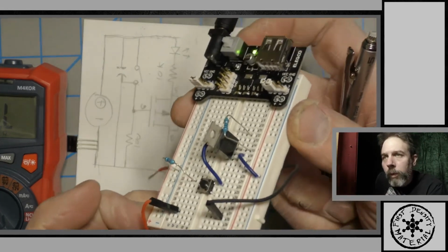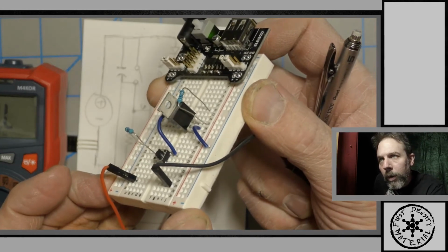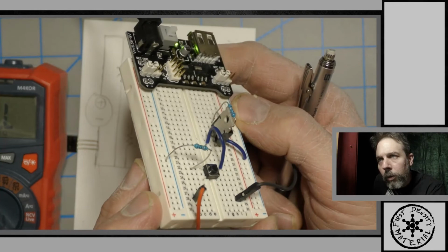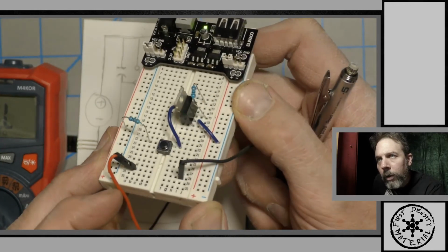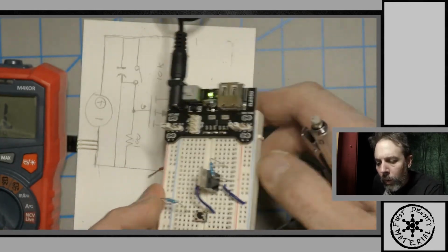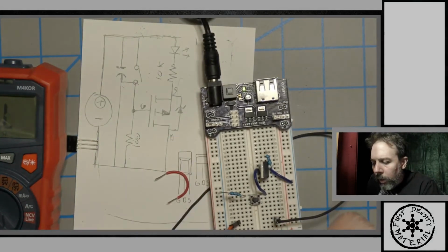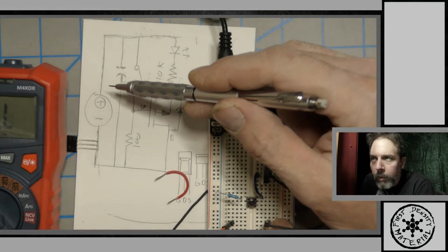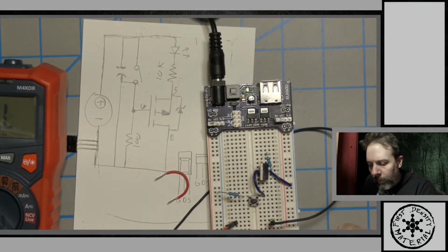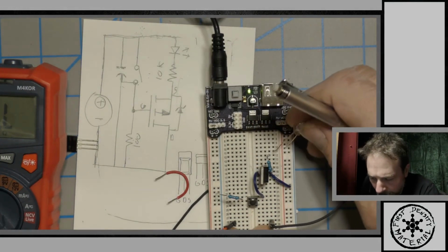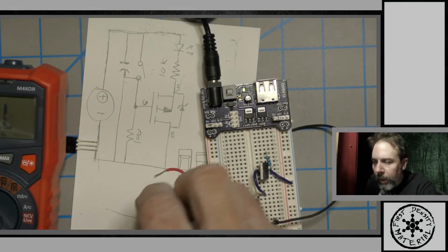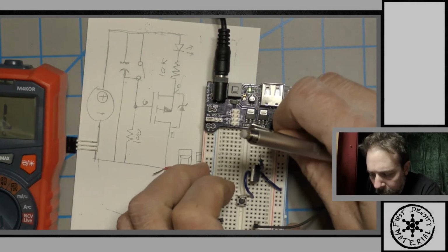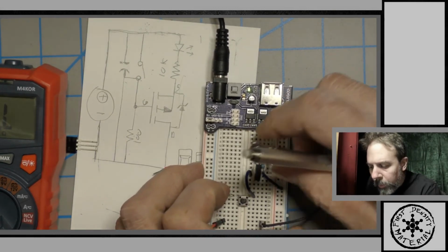And just so you have the view so far of it, in case I'm getting too fast for you, it looks like that. If you look, the LED's positive is hooked up straight to positive, and it's feeding the negative from the MOSFET. So the longer leg of the LED is hooked into the positive channel, and boom, it turns on.